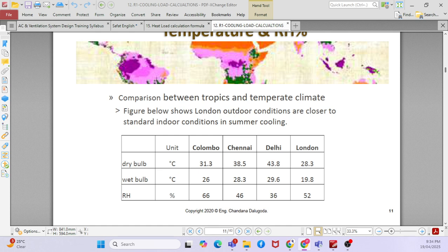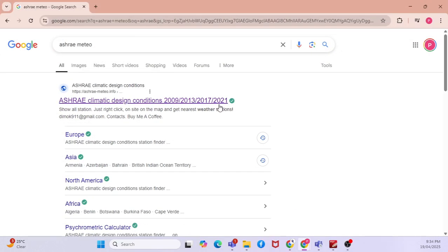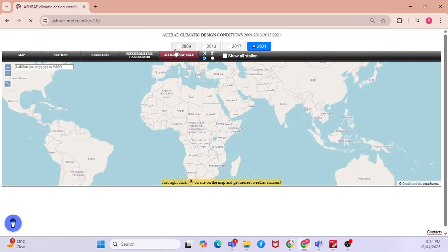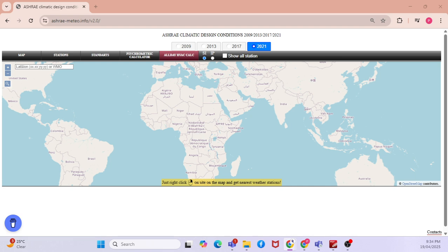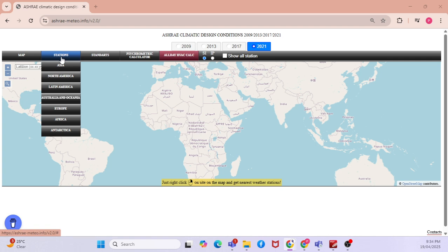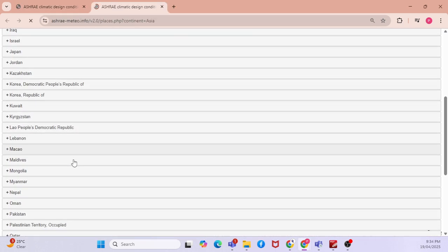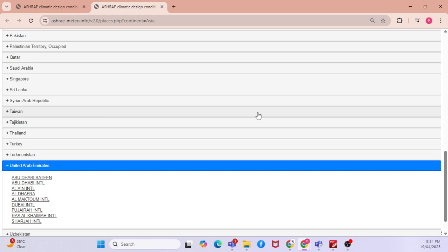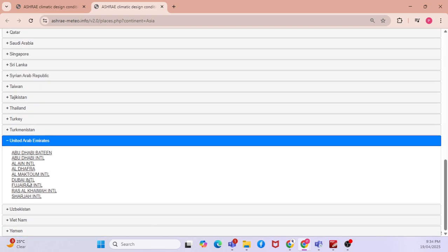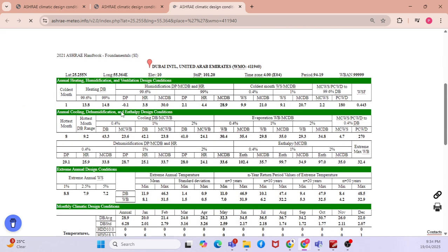What you are going to do, I'm going to share one more thing: ASHRAE. Can you see this ASHRAE Meteo? This is the ASHRAE Meteo climatic condition. Click here. This link I will share with you right away. When you open here, say, for example, this is a station, Asia. Further down, you have the United Arab Emirates, for example. You can go to any country in the world. Then go to Dubai International, and you will find the weather properties.